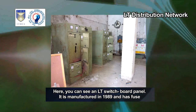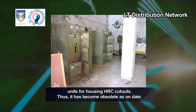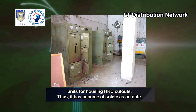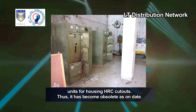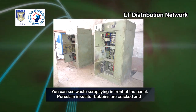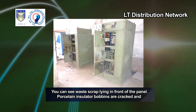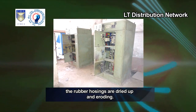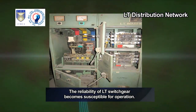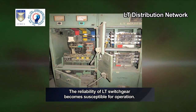It was manufactured in 1989 and has fuse units for housing HRC cutouts. Thus, it has become obsolete as on date. You can see waste scrap lying in front of the panel. Porcelain insulator bobbins are cracked and the rubber housings are dried up and eroding. The reliability of the LT switchgear becomes susceptible for operation.